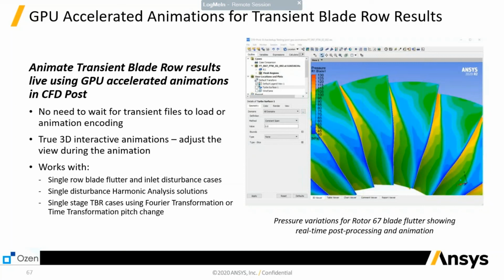In general, CFX is very powerful in case of blades, with a little more options or capability compared to FLUENT. FLUENT did not get an update. I think whatever was regarding fan modeling inside the 2020 R1 and R2 are, I would say, identical, except this one, which is in CFX.